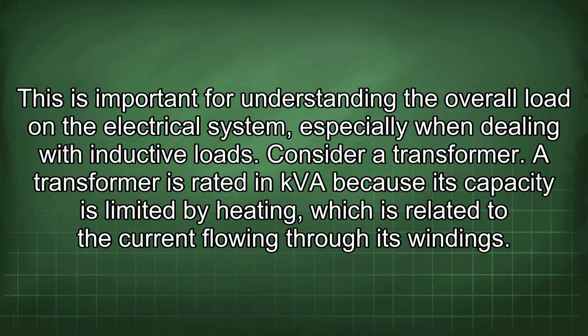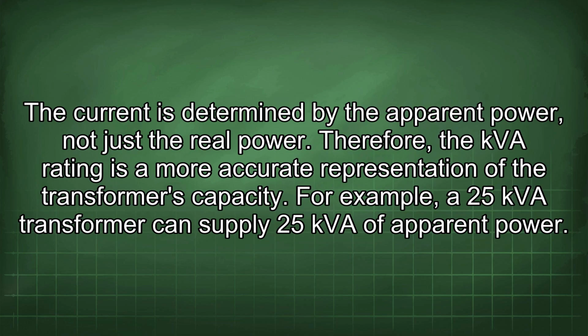Consider a transformer. A transformer is rated in kVA because its capacity is limited by heating, which is related to the current flowing through its windings. The current is determined by the apparent power, not just the real power. Therefore, the kVA rating is a more accurate representation of the transformer's capacity.